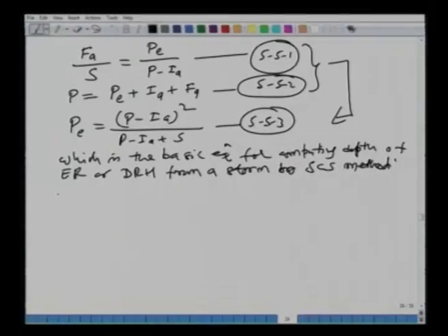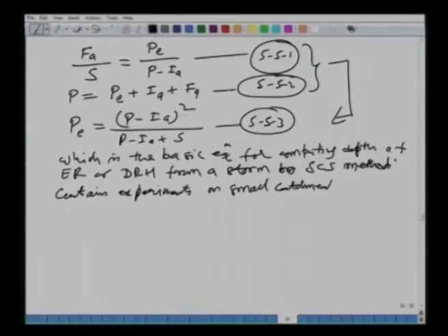However, if there is no information available, they have said that, based on certain experiments which they conducted on small catchments, again, this is not going to be applicable to the large catchments. So, for the small catchments, the SCS has found that your initial abstraction is about 20% of your maximum retention S.